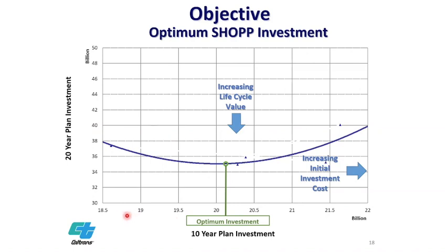The other thing is that if in your 10-year plan you only use those chip seal, preventive type of treatments, when you evaluate your entire system again, you see that in 20 years you really need a total investment similar to what you'd need if you invested a lot more in your 10-year time. So there is an optimal point, a good combination of strategies in your 10-year plan. These two dots represent that optimal point.